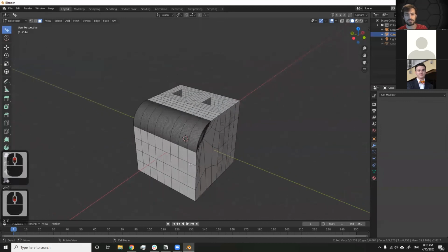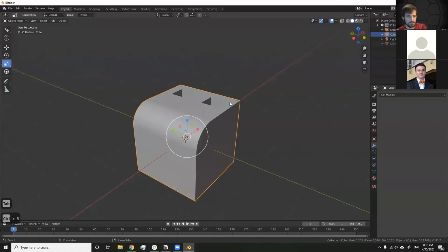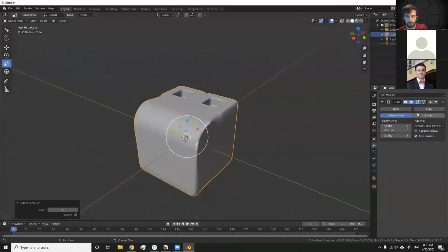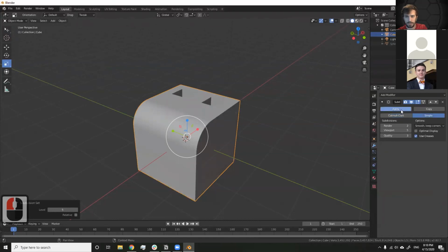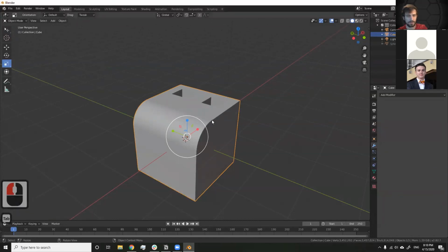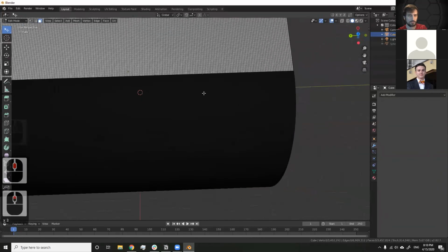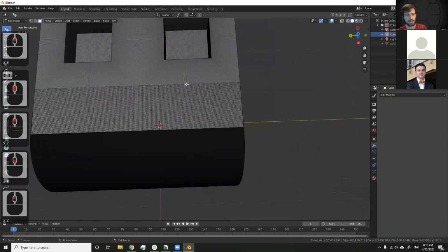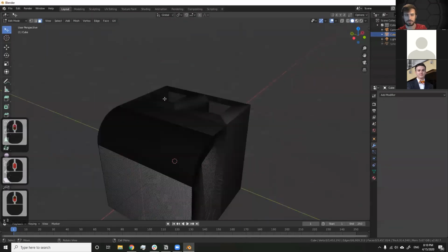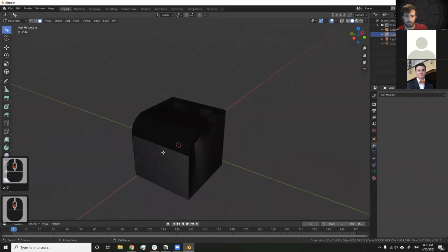So if you wanted to add sculpting onto this, you could, for example, add on a subdivision 5 modifier to it with just a simple modifier, hit apply. And now if we go into tab again, it's going to take a second because it has a lot more faces to it. If we go into tab now, we have tons and tons of faces, very, very small polygons across it. So now if we wanted to sculpt, we have a lot of polygons to work with and you can get some smooth sculpting. Whereas if we tried to sculpt with our original one where we had these big blocky shapes, it wouldn't sculpt as smoothly.